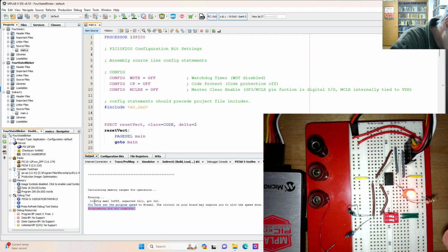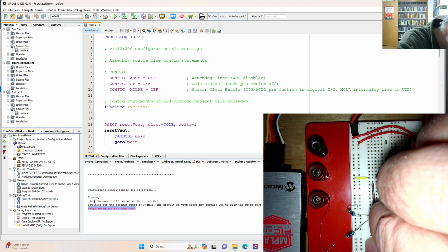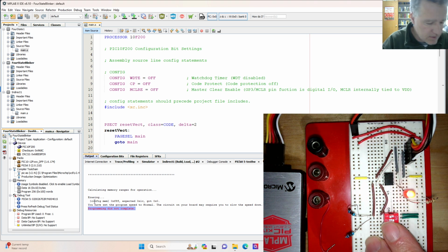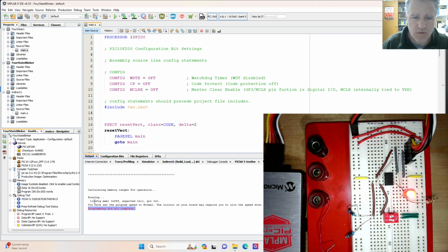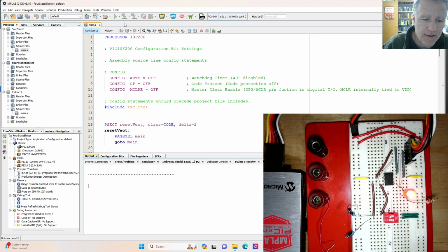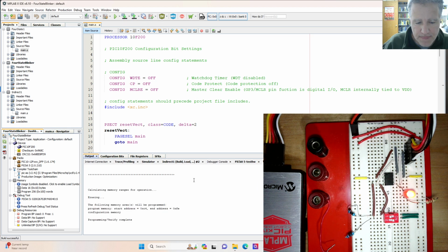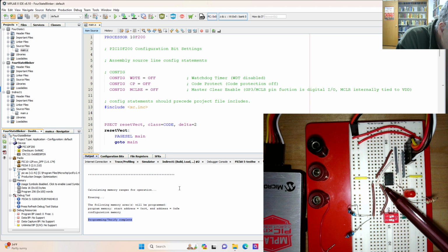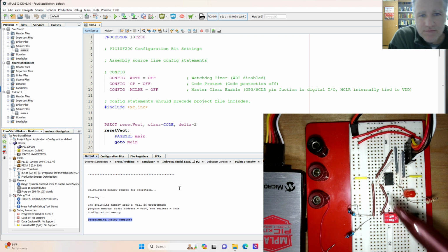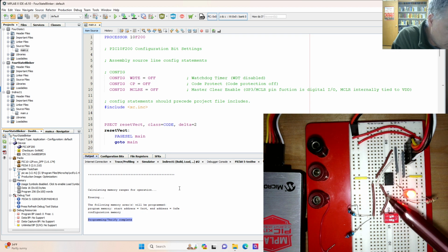Now, notice I'm going to change just the 1 pin. Is that what I want? Yeah. So this is on GP1, and I'm going to change that to 1. And let's run this again and see if we can get it to be successful. And it is. So programming complete. So notice what happened: there's a pin that goes to the same pin as GP1, and if that's in the plus 5 volt position, it somehow interferes with the programming and blocks the programming.